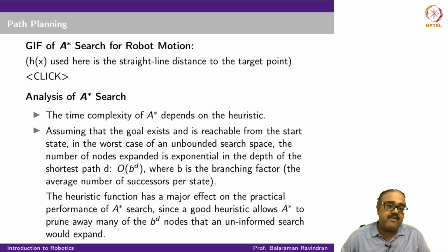But in more complex environments, people prefer what are called probabilistic path planning algorithms, where you do small amounts of sampling of the world to figure out whether you are going in the right direction, and these return feasible paths and might be optimal, but they typically don't guarantee optimality. They return feasible paths, but they do so much more efficiently than something like A star or Dijkstra's.